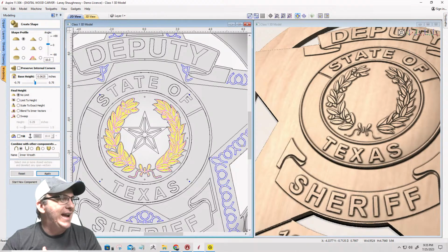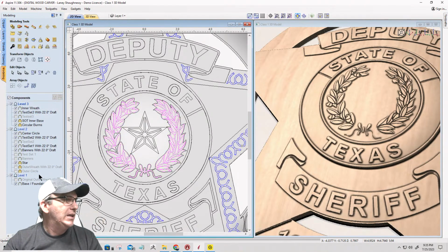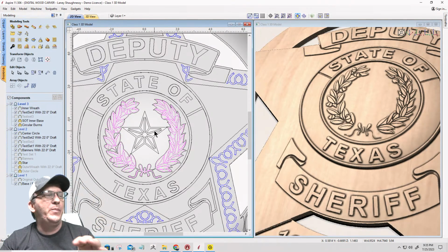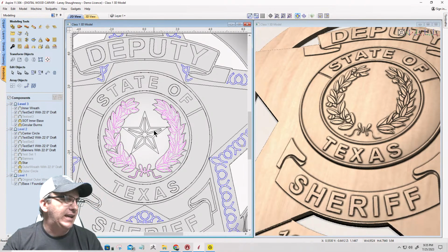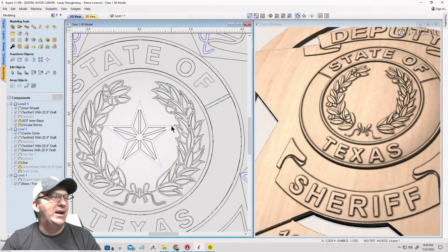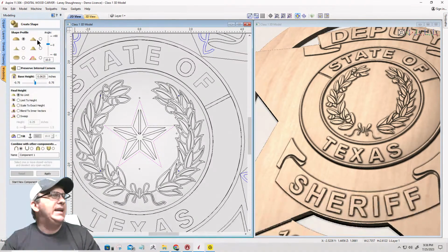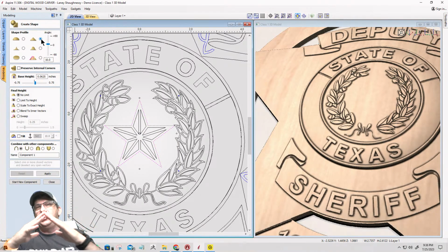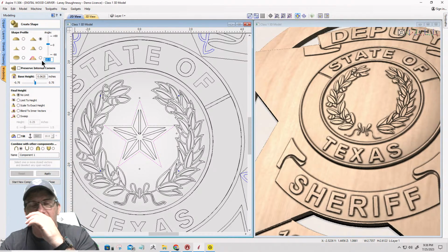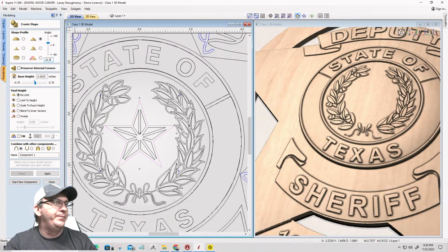All right. So now, close out of this very quickly. Actually, no. Let's go ahead and get the star built, and I'll do a draft on both of those two things together. Let's get the star built. Now, for the star, I'm going to do the outer boundary here. This shape, I want it to have kind of a pyramid shape to it. Now, this is going to be based off of angle, right? 45, that kind of thing. I'm going to go with a 22.5 degree angle on this pyramid type shape for this star.